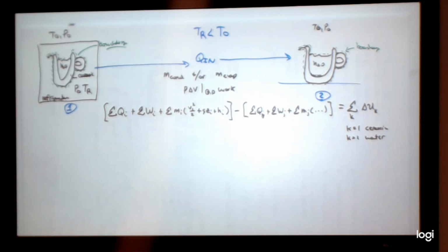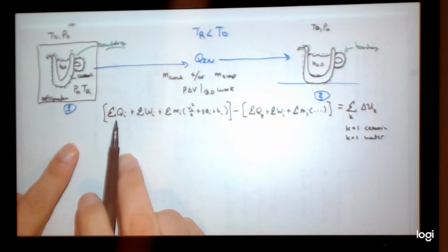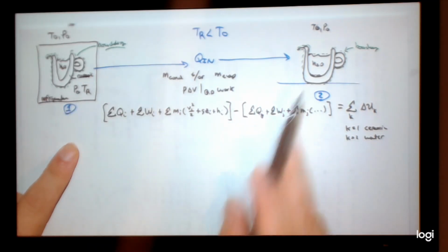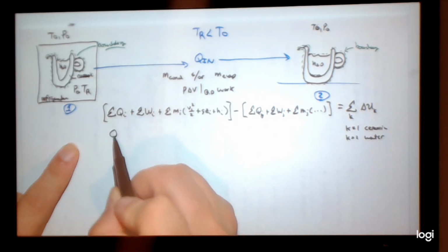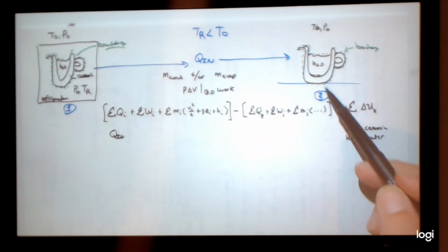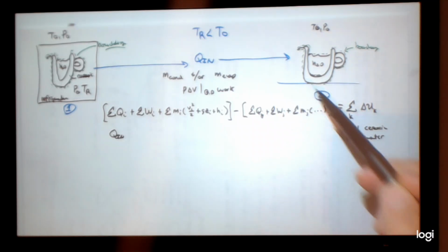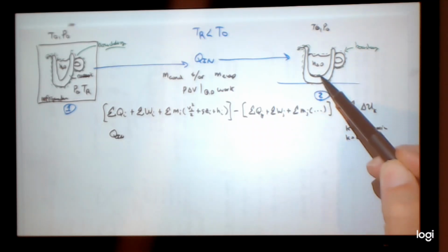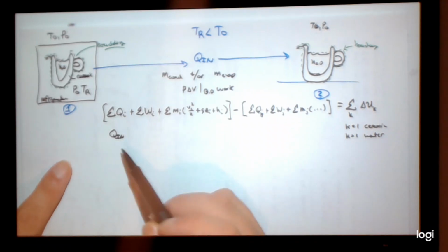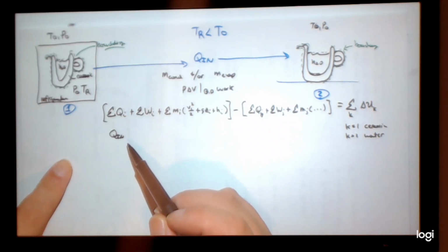Okay? And then heat in. Yes, from a practical side, there's some heat in, so let's just say we have some Q in. When I talked to some students, they said that there was some heat in, but they put two forms of heat in, one from the counter into the cup and one from the air into the cup, which is fine. You can do that if you want, or you can just say that there's some net heat into the system, okay?